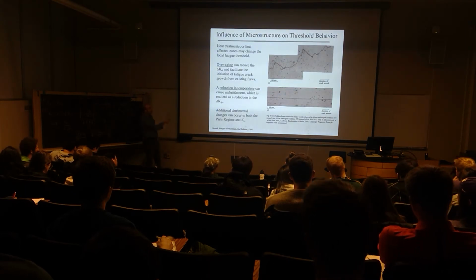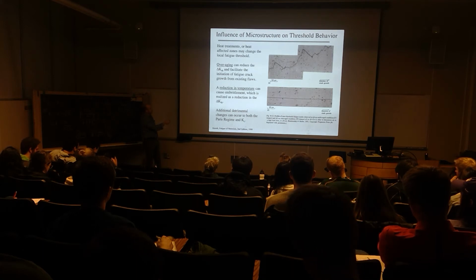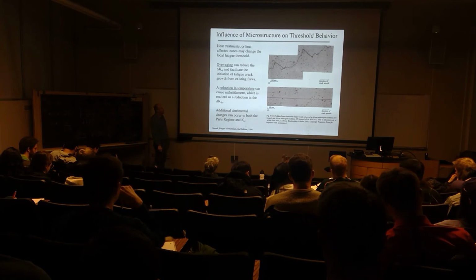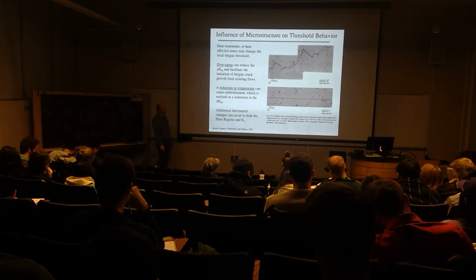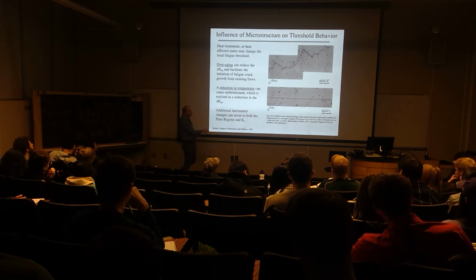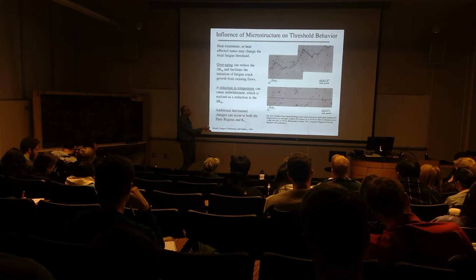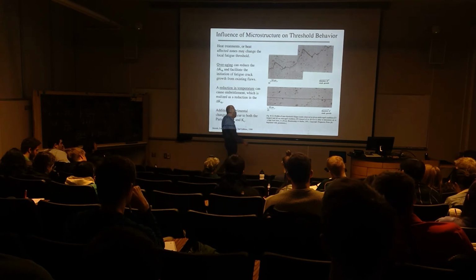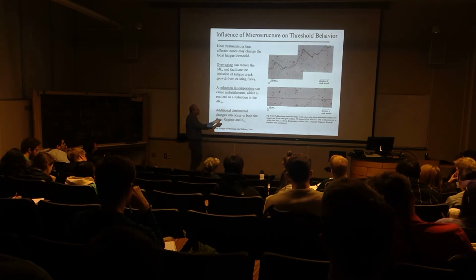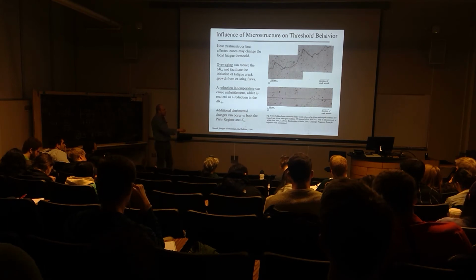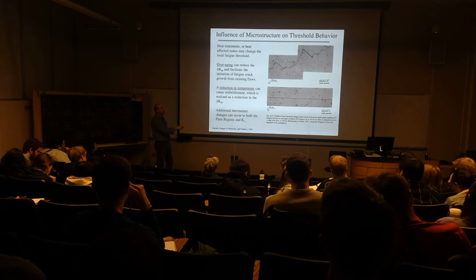So one of the things is overaging. Overaging, which is very, very common in aluminum alloys, can reduce that delta K threshold and enable fatigue crack growth to initiate from existing flaws. These are two different near threshold regions of fatigue crack growth response. You've seen a cross section for an aluminum, copper, lithium alloy which has been tested without overaging, okay, that means in the T3 temper, and then after overaging, and you see what happens.